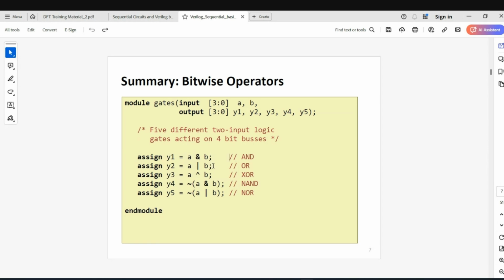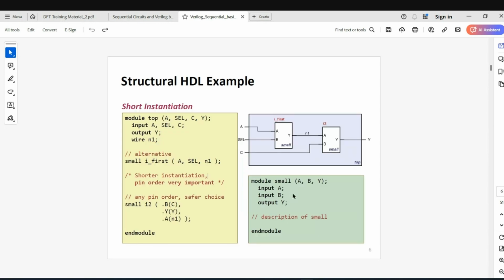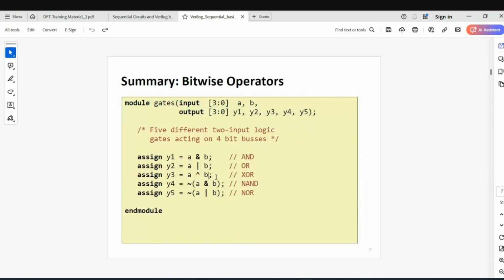When you write these and give them to the synthesis tool, because RTL has to be synthesized to gate level to start working for the physical design team, or for the DFT team also if they are using a netlist flow, the tool will convert these symbols into the XOR behavior. The tool will find a suitable XOR gate from the libraries, as you saw in the previous image, and instantiate it here. So once you synthesize, it will get converted like this. Then you will have a proper gate representation of these gates. You will not have symbols. So assign is one way to represent.